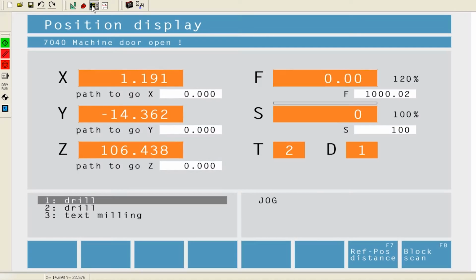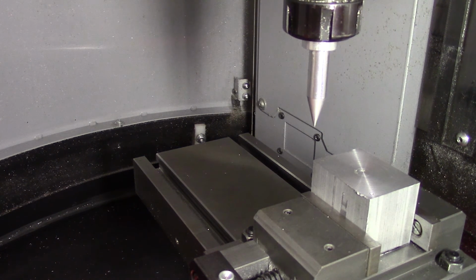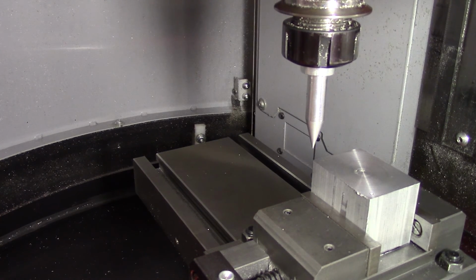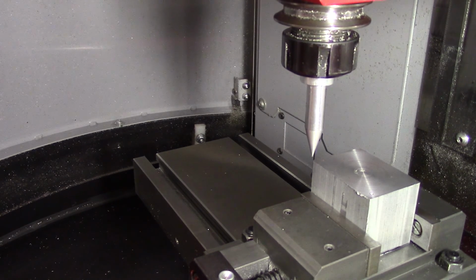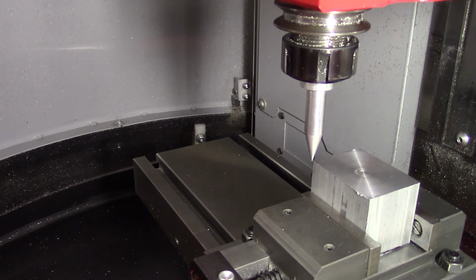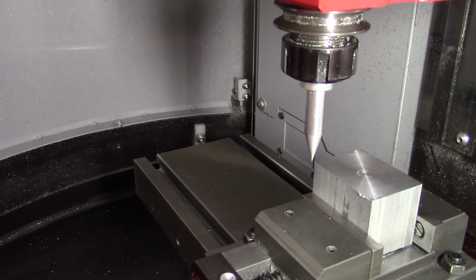Now I'm at 120% here. I've got to reduce that in order to stay safe and not impact on the top of my work. So I'm going to drop that to 5. Actually, I'm going to make that a bit quicker, 20. And as I get closer, I'll just slow that down. Move that left a little bit.